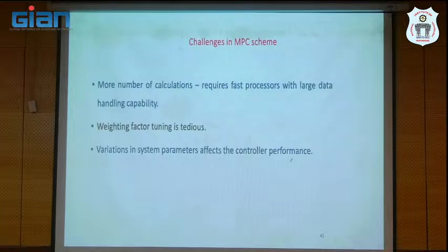Otherwise, if you express torque in terms of current as well as flux in terms of current, then you take Id and Iq. What is the advantage? Both the torque control variable and the flux control variable are in amps. In that case, since both units are the same, you need not go for a weighting factor. We can eliminate the weighting factor. That's why transformations are required; without transformations, we cannot eliminate the weighting factor, right?